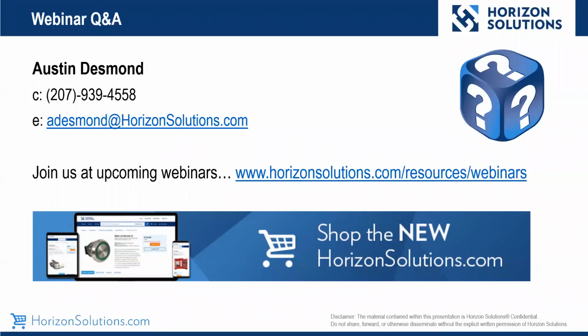And if you perform all your calculations at average or at best case scenario, the likelihood of someone injuring themselves, especially as time moves on and that machine degrades, wears, things like that, you're not truly protecting the employees at that point. Doing it at worst case ensures that through multiple faults, through a slowed down machine, through communications issues, you will still have a safe machine.